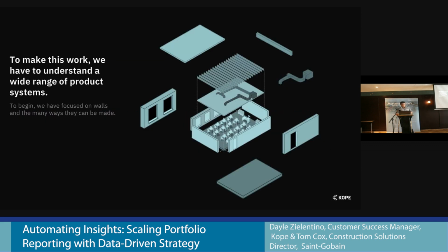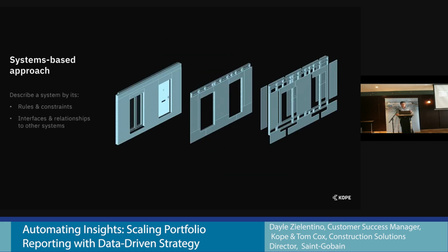We spend a lot of time understanding this logic. So with the Interval team, we understand how boarding and systems go together. We understand that you can't share studs for fire. We understand how slam tests need to be done, so you have to have clearance for boarding so those things don't break when someone slams the door or the wind catches it and that sort of thing. And we encode that and bring that into the system and logic so those pieces are understood.